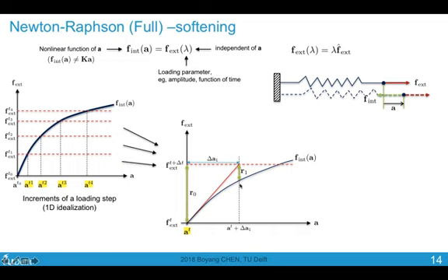Then this point is fully known. I can calculate the gradient. And now I can use the gradient and divide the residue after the first iteration by this gradient. I can get a new estimate for the incremental solution. So this is the correction. This is the first estimate. And the first estimate plus the correction would equal the second estimate for the delta A incremental displacement solution. I can repeat the procedure until I reach convergence.